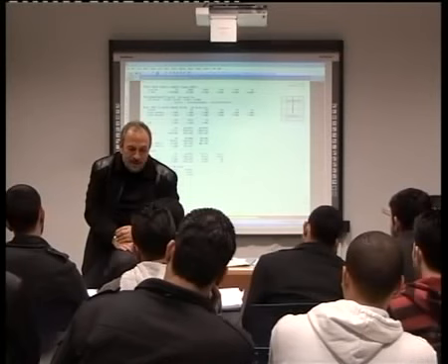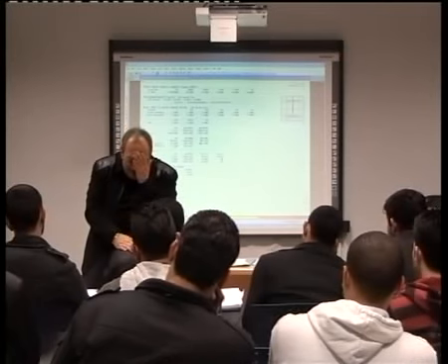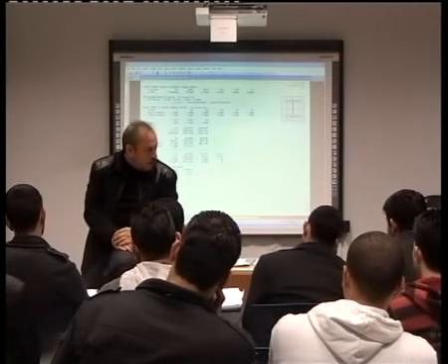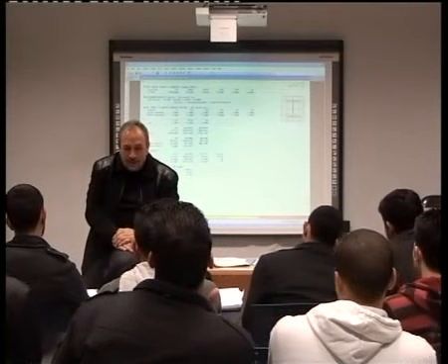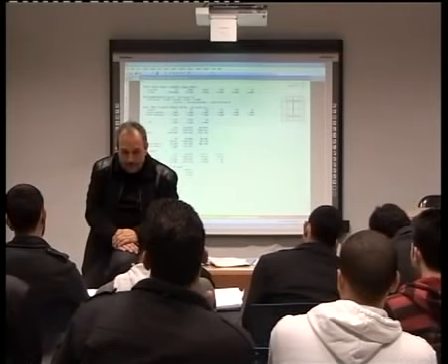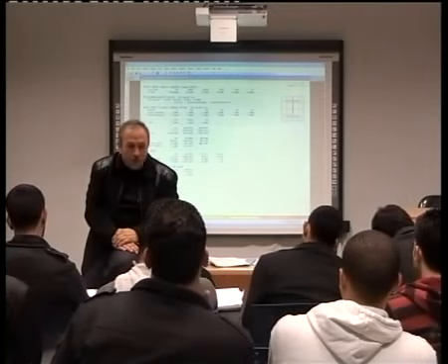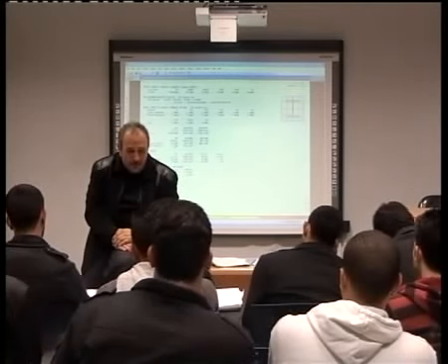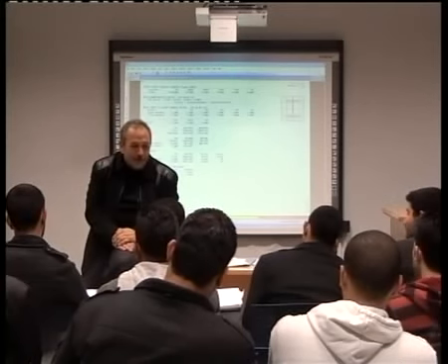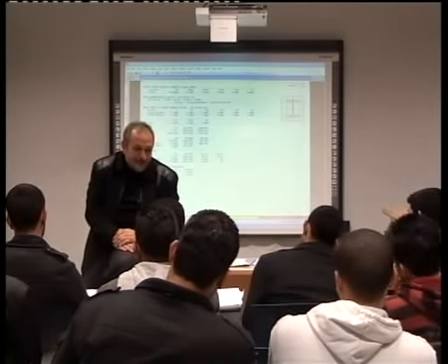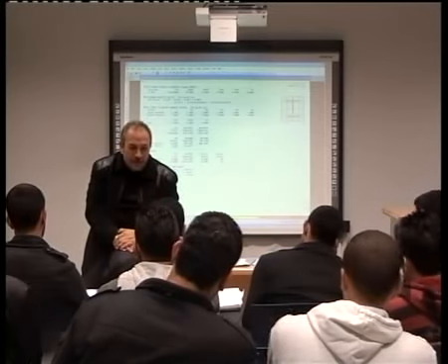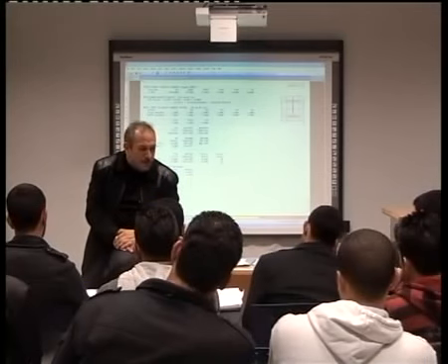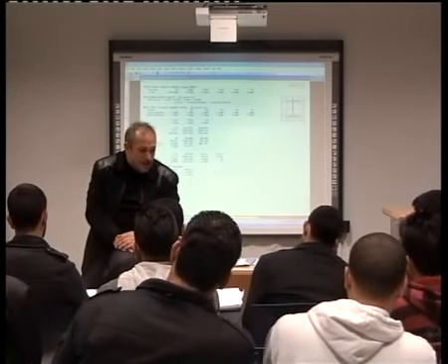I speak these to you because I saw many engineers in the field. They only use SAP, and they provided us with data that is completely illogical. A few days ago, someone told me, I've got a 5-meter retaining wall. Do you think 20 centimeter is enough to carry it? Retaining wall. What do you think? It is cantilever. What is the depth in your feeling? The depth, height divided by what? By 7 or by 10, by 8, by 7.